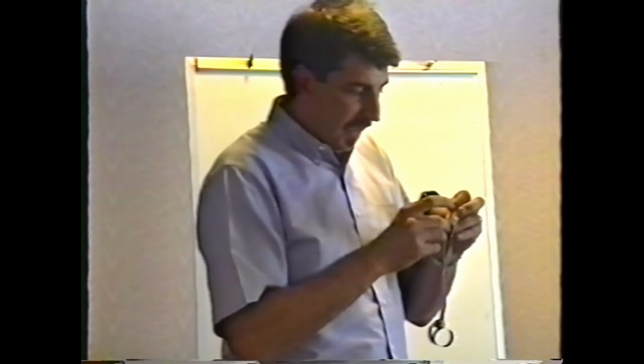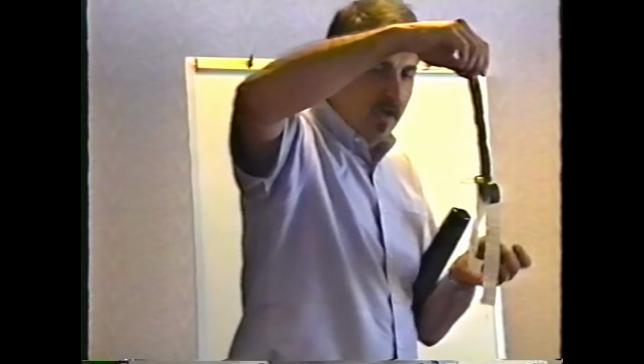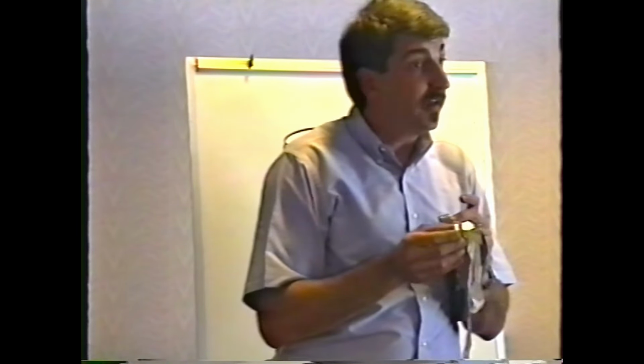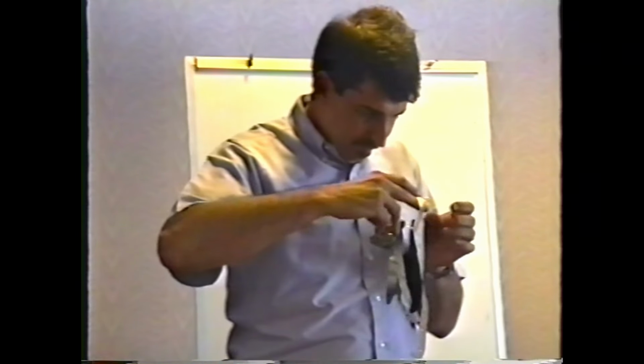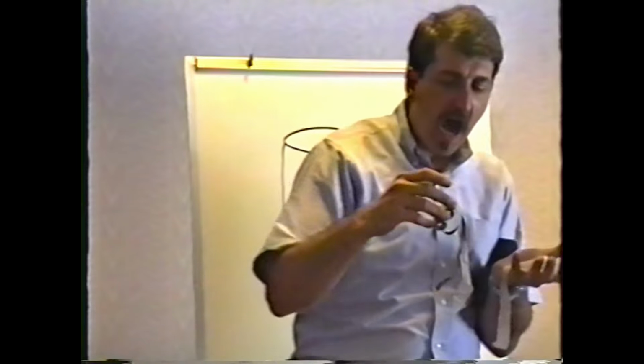Here's the paper, and what you see here is these two sheets of aluminum foil, and separating them is this paper soaked in something called electrolyte. The electrolyte is like, in your car battery, the acid, that's electrolyte. Or in a dry cell battery, if you've ever seen a leaky dry cell, the stuff that's leaking out is electrolyte. Technically, electrolyte is something that allows something called an ion to migrate.